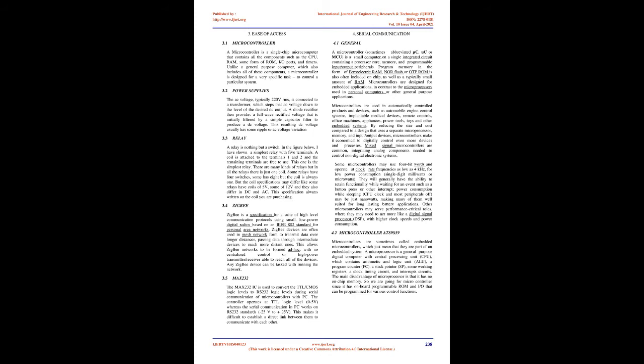A microcontroller, sometimes abbreviated µC or MCU, is a small computer on a single integrated circuit containing a processor core, memory, and programmable input/output peripherals. Program memory in the form of ferroelectric RAM, NOR flash or OTP-ROM is also often included on chip, as well as a typically small amount of RAM. Microcontrollers are designed for embedded applications, in contrast to the microprocessors used in personal computers or other general-purpose applications. Microcontrollers are used in automatically controlled products and devices, such as automobile engine control systems, implantable medical devices, remote controls, office machines, appliances, power tools, toys, and other embedded systems.